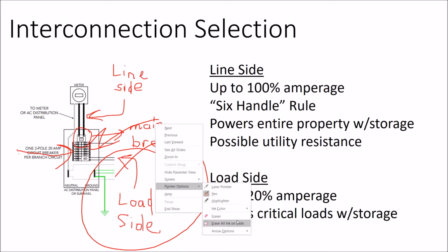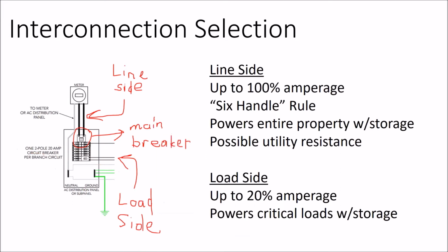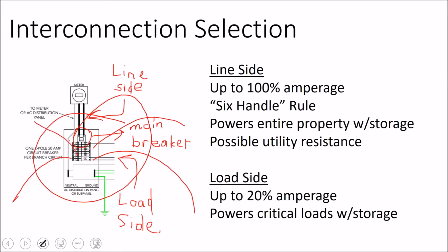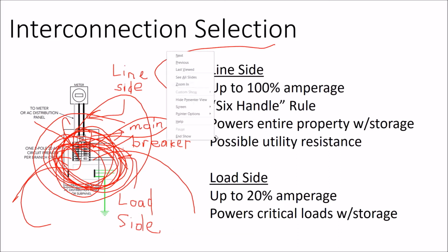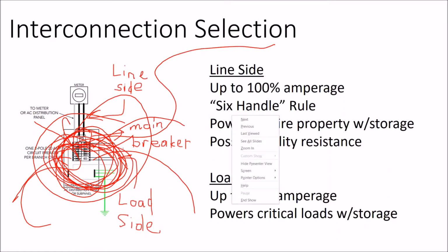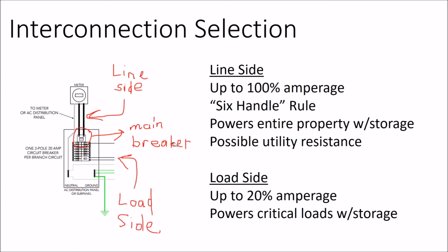Now in commercial design, you're generally having a dedicated panel, and this might be like a 200 amp panel, and you might be tying in 200 amps of solar into it. So if the total breakers of this panel do not exceed 200 amps, then you can just tie in the solar wherever you want. But usually on a residential panel, your service panel is overloaded and these additional National Electric Code provisions apply.